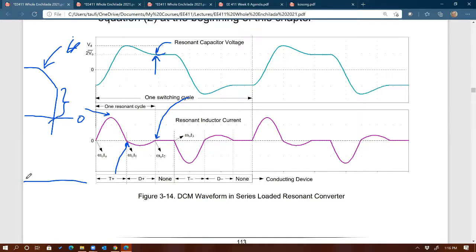Maybe more. So if the diode current reaches 0 when you turn it off, then what reverse current are we talking about? There is no reverse current, because it goes to 0 naturally. In the first case, you are forcing the current to go from some amperage to 0 right away. In that case, yes, you will have the reverse recovery time.